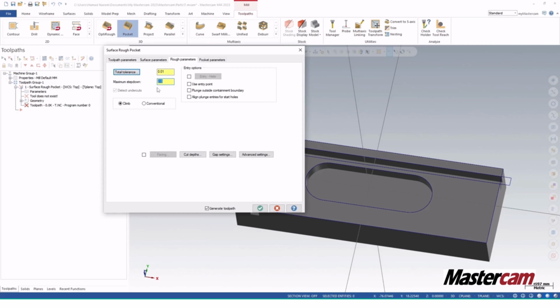The step down means how much cut it will take every time it enters the workpiece. So it's 2 millimeters. It's too much cut for the 10 millimeter tool, so I just make it 0.5 millimeter.